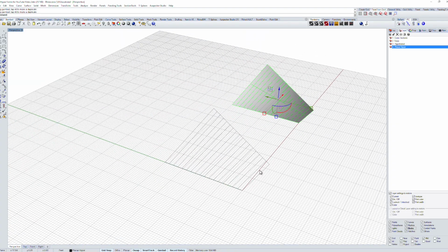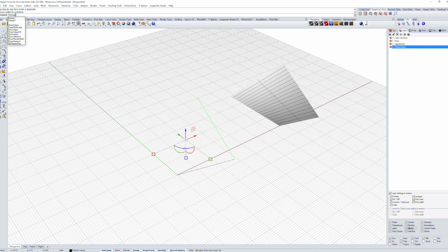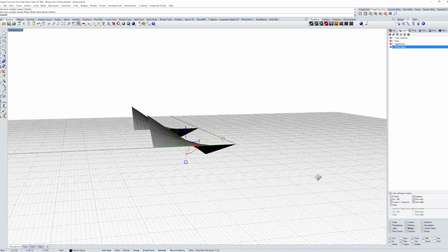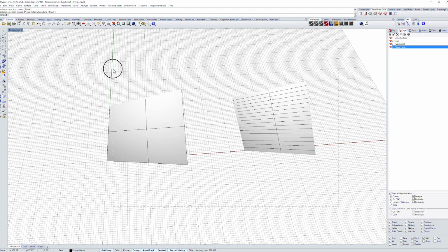So we can generate this ruled surface also with the sweep command. So maybe I'll delete these guys here and take these two edges here as the rail. And I'm going to do a sweep to rail and use this curve. And you see we generate our surface once again. So it can be swept, it can be lofted. Those are both two ways of doing it.